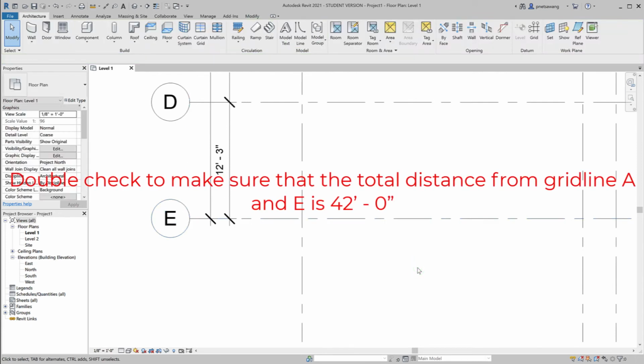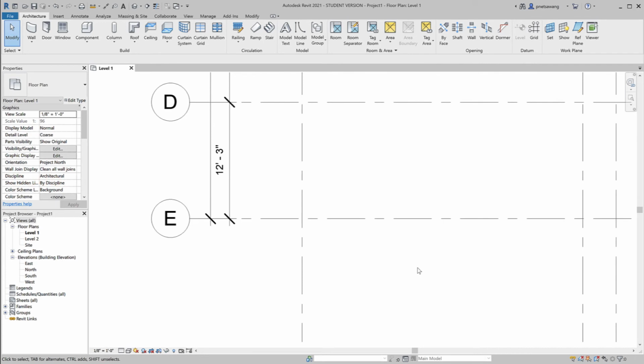With regards to the sketch then modify method, there are a few mistakes that beginners make. First is forgetting to select the object that you want to move, then going directly into the blue colored dimension. By making that mistake, the intended object that you want to move will stay in place and the unintended object selected will get moved instead.